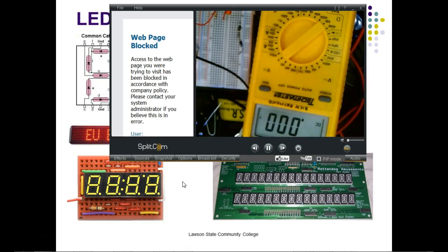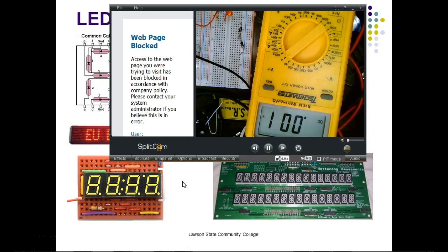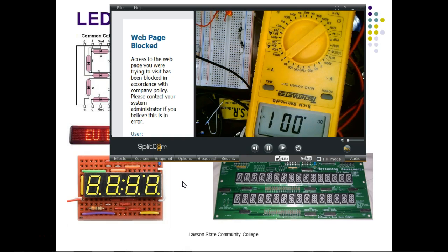Your screens either use fluorescent bulbs, or now they're moving to LEDs, and they call them LED displays, but they're not. They're LCD displays. They're just backlit by what? By LEDs. So when you hear LED displays, they are not LEDs. They're actually LCD displays, backlit by what? By LEDs, which gives us an advantage because they'll put thousands of nice white LEDs back there, and if one of them goes out, it usually doesn't bother you.